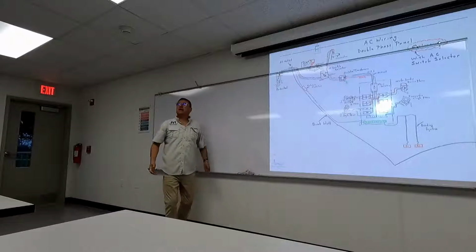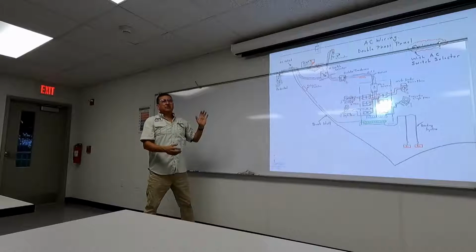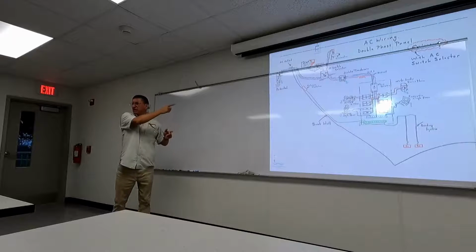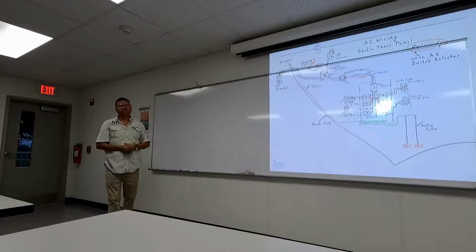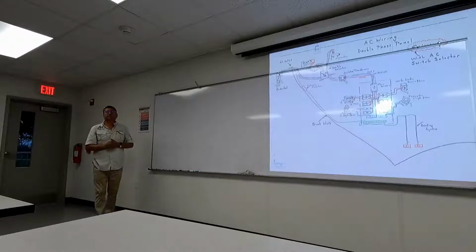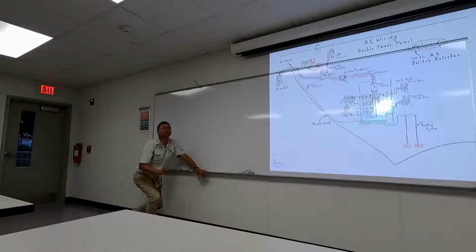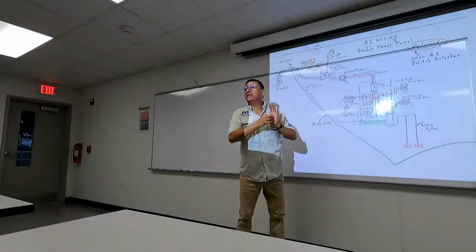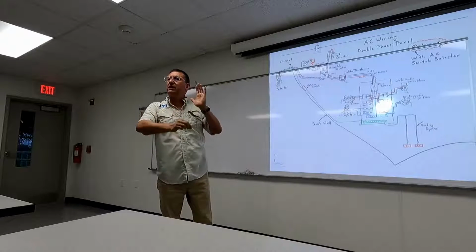Some people say, I have a metallic cabinet in my boat, but it's over the water line. Is it necessary to connect that metallic cabinet to the bonding system? Yes. How would you do that? Put a screw into the case, and a single wire. Yes, in the case, a screw and the cable. Later we are going to learn what gauge of wire is used for bonding.